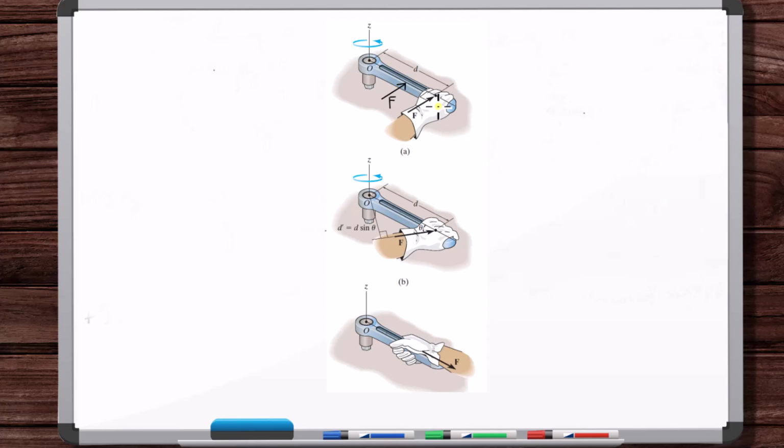Rotation about what? About a point. So, more specifically, the moment of a force is the tendency of a force to cause rotation about a point. What point? Well, you choose the point. Whatever point you pick, based on the nature of the problem, right? Because if we choose this point for this problem, well, then all of a sudden, this force has a greater tendency to cause rotation about this point than this force. So the moment depends on the point you pick.